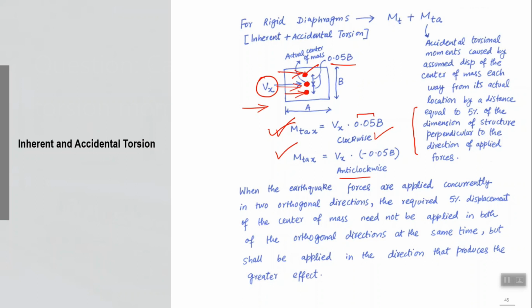So if we check X and Y together in the same pattern in ETABS, it doesn't mean that it is applying them together. It is still applying X separately and Y separately, and then it will report the results for both sub patterns separately.